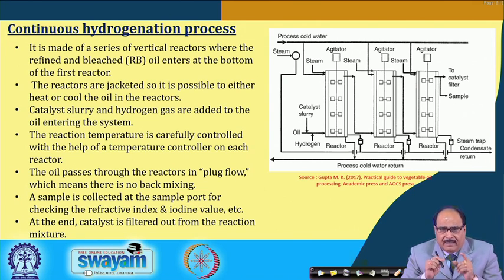The removal of the catalyst is very important, and the filter provided in the system should be perfect to remove almost all the catalyst present from the oil. Otherwise, if the catalyst remains in the solid fat, it will be problematic. So, all the catalyst has to be removed.